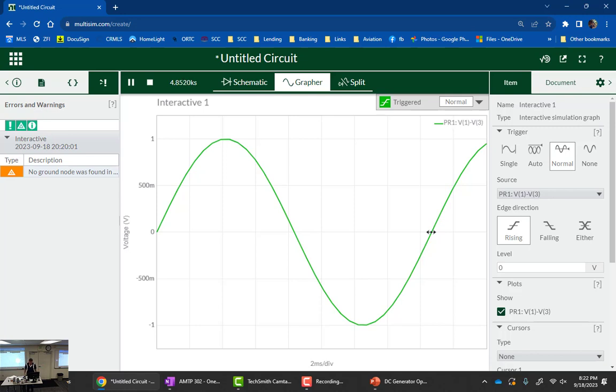8.3? Okay. We have 8.3 milliseconds. Wouldn't that be times 2, because you have 2 milliseconds per division? Yes, for each one. So 8.3 times 2 is 16.6. Yeah, and that lines up because you do 60 to. I got like 60. I didn't do the milli in there. Yeah, 16.7 milliseconds probably, because then it's 0.0167 seconds.